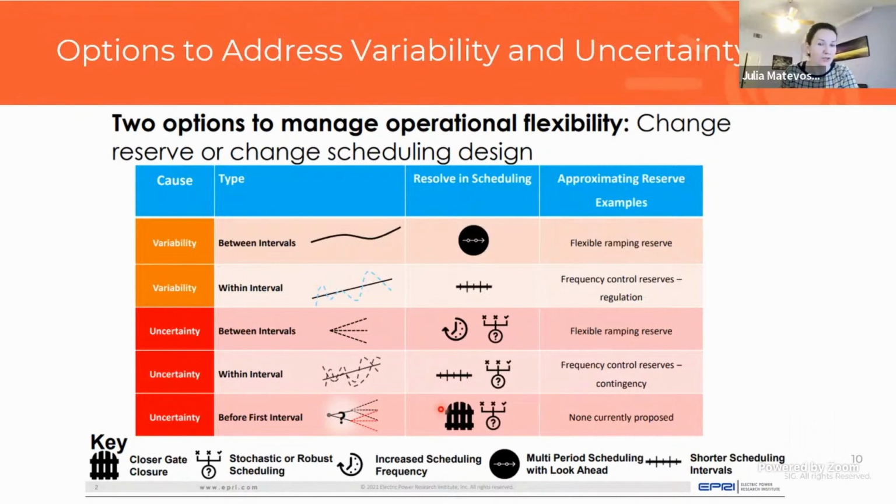But in some other areas, for example, in California, at least a while ago, I'm not sure if they changed that, they were running real-time dispatch 15 minutes ahead of the time when they use this dispatch. And so 15 minutes is a relatively long time. And during this time, wind can change, solar can change, load can change. So by the time you arrive at this operating interval and you send this dispatch instructions to generators, you're already facing a large error.